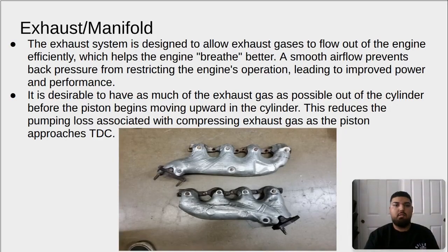Exhaust manifolds. The exhaust system is designed to allow exhaust gases to flow out of the engine efficiently, which helps the engine breathe better. A smooth airflow prevents back pressure from restricting the engine's operation, leading to improved power and performance. It is desirable to have as much of the exhaust gas as possible out of the cylinder before the piston begins moving upward in the cylinder. This will reduce the pumping loss associated with compressing exhaust gas as the piston approaches top dead center.